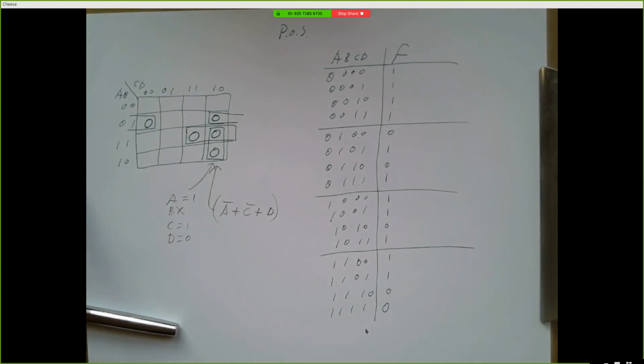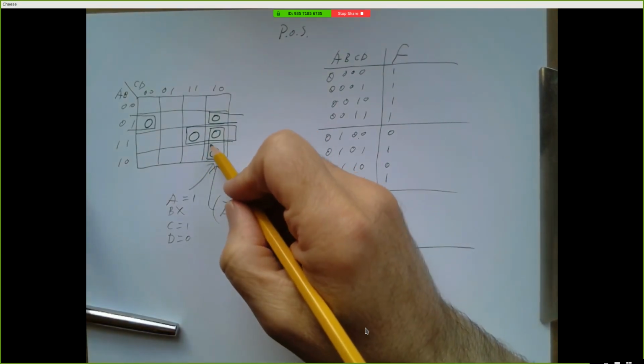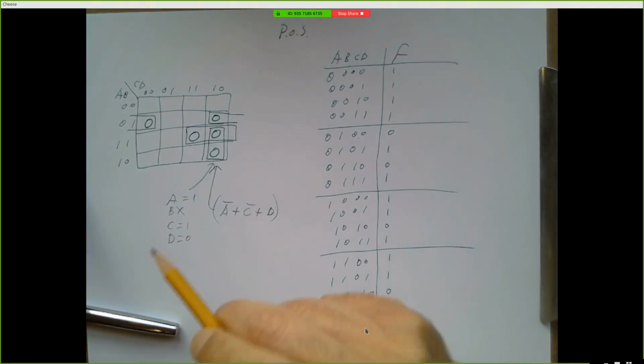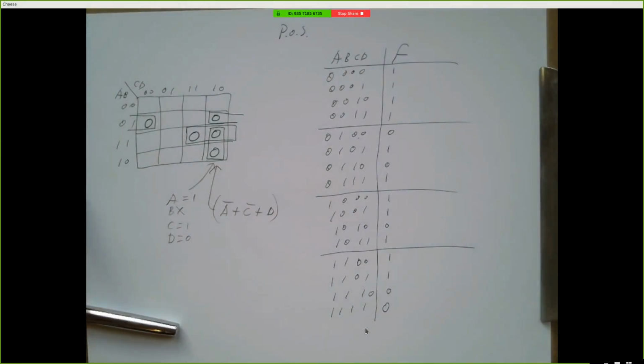So should you overlap boxes to avoid having a term in its own box? If you can avoid having a single term by itself by overlapping, yeah, definitely overlap. Right, so I could have just done a 1 by 1 here, but that would have given me a sum term with 4 elements in it. So yeah, get a bigger rectangle by overlapping. Gotcha. I was avoiding overlap. Okay, no, the overlap is good. It usually means that things are going well.